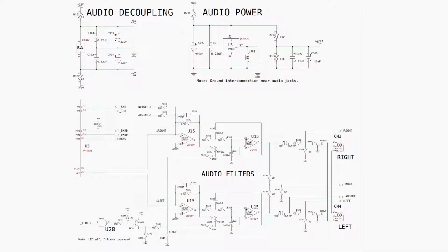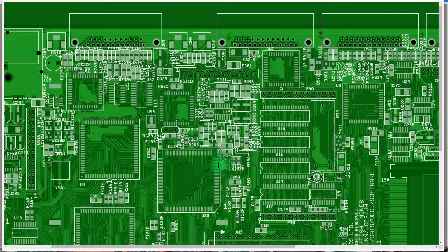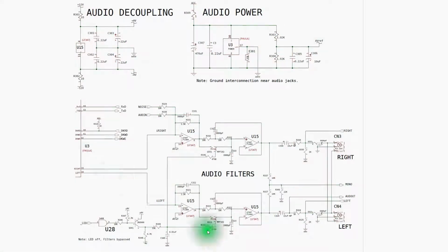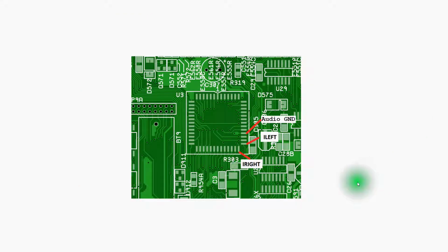If we come back around to this interactive interface, the next thing I did from this was I did some screen captures on it. Let's go to the end here. So I did a screen capture of where the Paula chip is on the board, and I actually added labels using the signal names that I'm using to make it easy to identify the pins. I can look at the picture printed out and just know I want to touch a probe here, I want to touch the probe here, and I want to very carefully touch the probe here, and just see what I see.